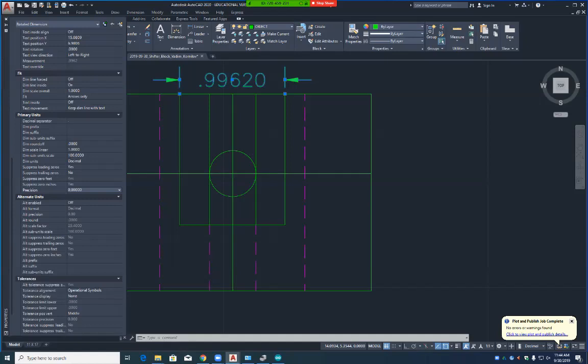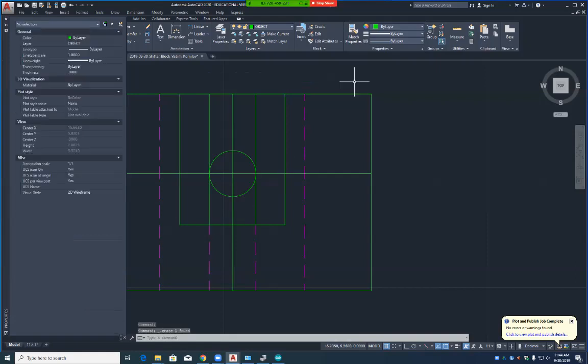Okay, so what I could do now is I actually found one, so I'm going to move this one from there to there. I'm going to offset now. How far does the center line come out beyond here? A quarter of an inch. So just offset that. Extend that center line up. Got exploded. Right.